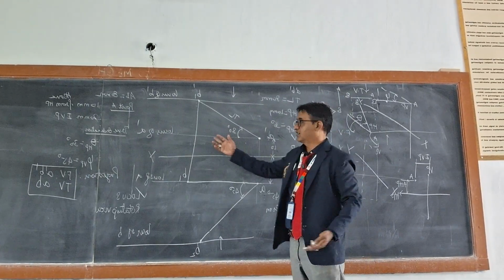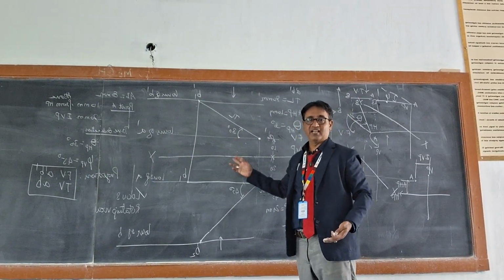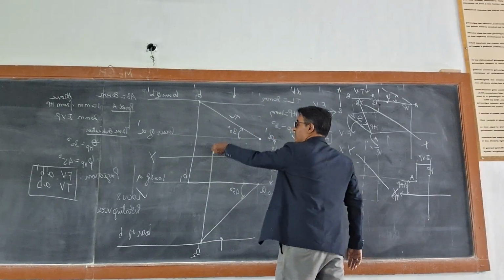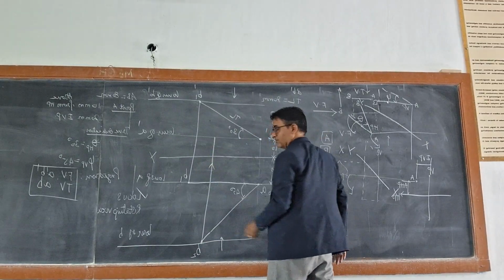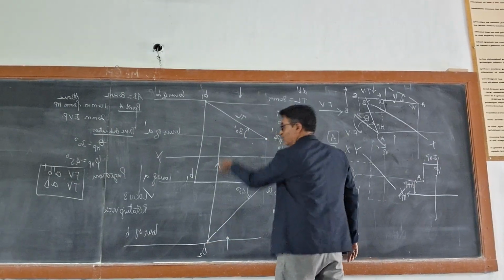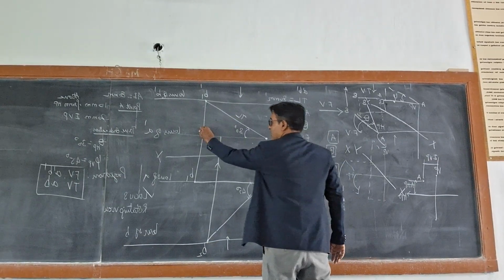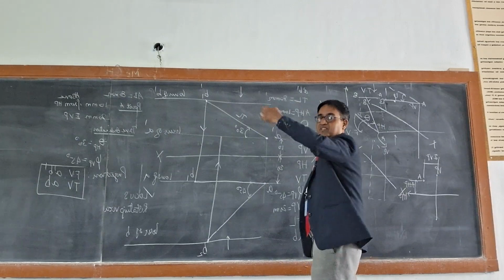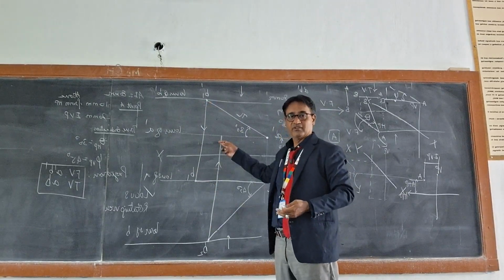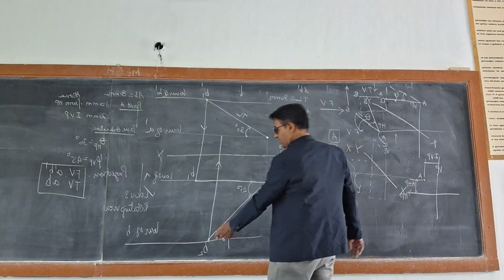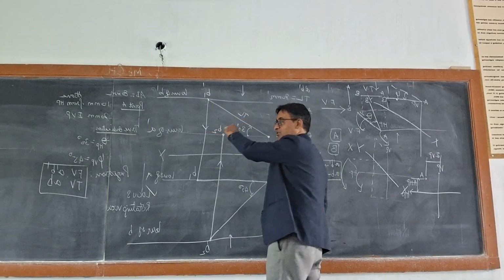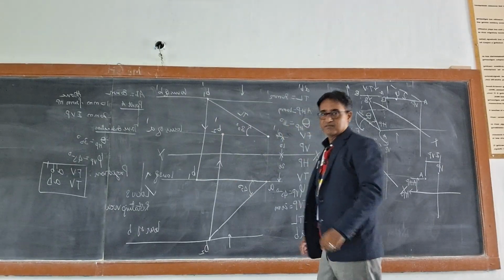All this will be projected onto the reference line XY. Therefore, you take this up, put an arrow mark, meaning the line is drawn from the bottom point B2, it is moving up. And similarly here put an arrow mark to convey that it is dropping down, it is bottom up, right? Now this point is B2, therefore here it will be B2. Since it is in the front view, add a dash, B2 dash.